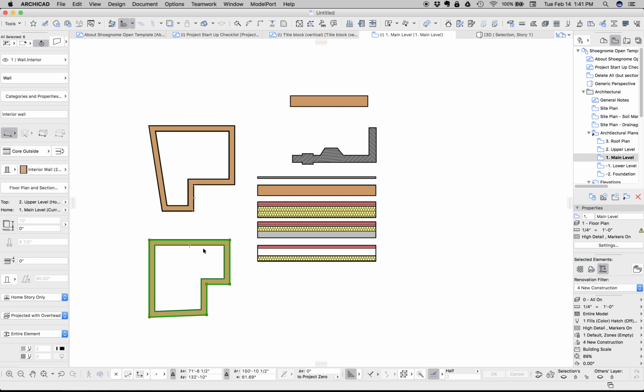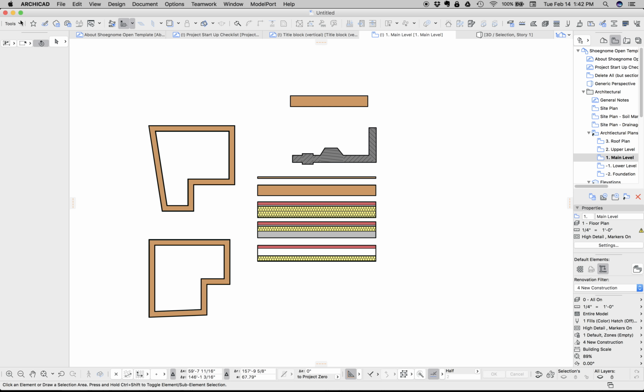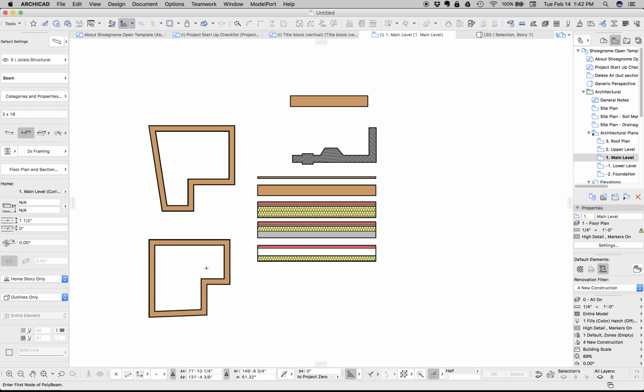This is awesome because it means anytime you use the wall command to create a chain of walls or any other tool that can do this, like the beam tool, the elements will be created and grouped. So let's actually go to the beam tool and I'll show you. Let's hold down the space bar, click on that, and there we have it. I've just created a bunch of beams and they're all automatically grouped. Huge time saver, something I always have on, something you should always have on.